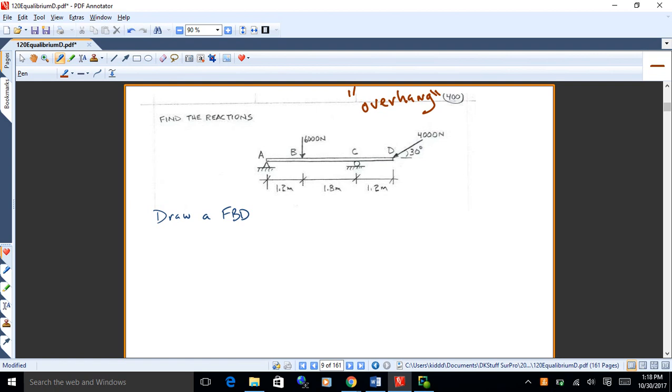So look at what motion C prevents and put in a force to mimic that. Look at the motions that A prevents and put in forces for those, okay? And I would suggest just using the sketch itself, because it's quicker and more direct and it's all dimensioned and good to go. So you probably just need a couple arrows in there. Maybe 3 arrows actually.